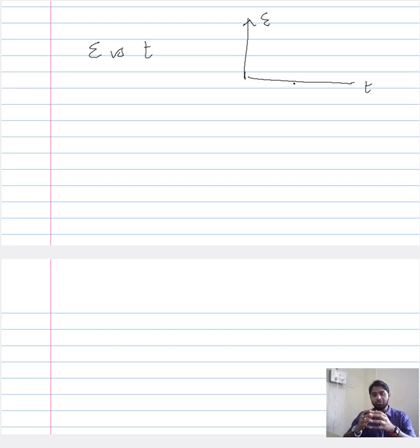Therefore, in order to ensure that a constant mechanical condition is applied, instead of imposing a constant load, what is usually done is we ensure that the stress experienced by the material is constant, particularly not with respect to the original cross-sectional area but the instantaneous cross-sectional area.